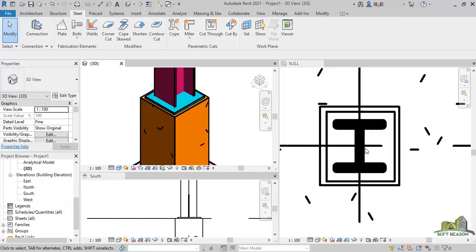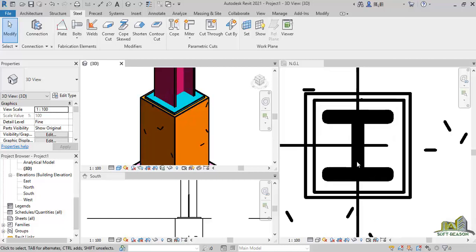In this one I want to add an anchor bolt to it. For me to be able to do that, I will use this bolt tab. Click on the drop down menu, select anchor bolt. After selecting anchor bolt, I want to just highlight it that way, so that the cursor will change to this. Once the cursor changes to this, you can bring it here, to this place.